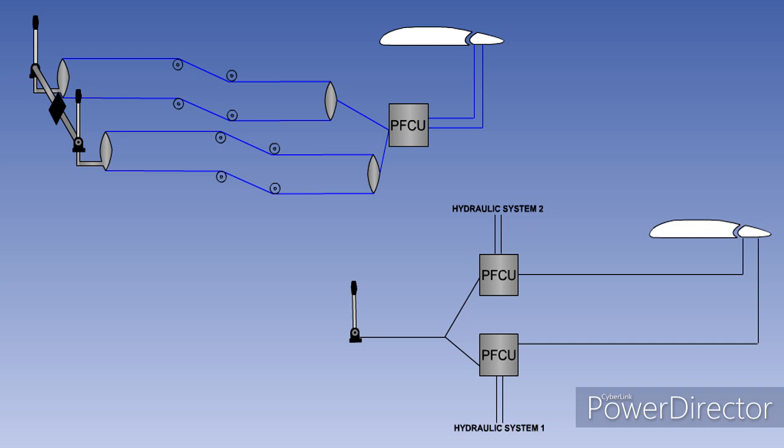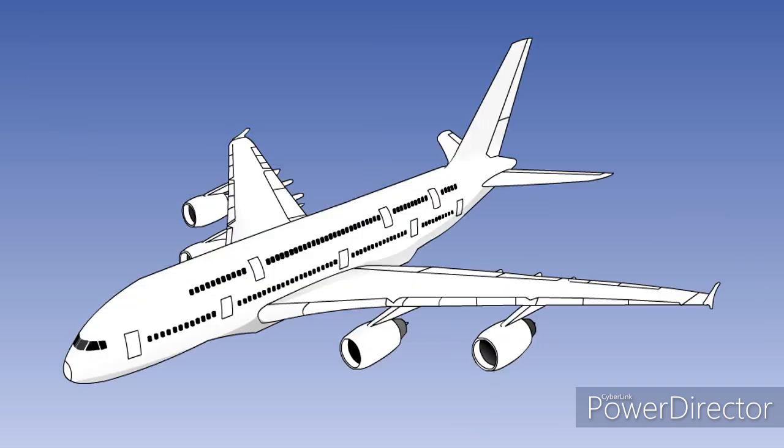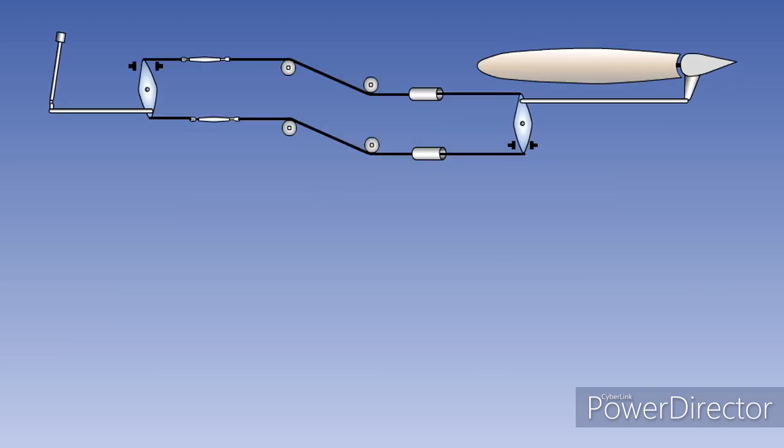In this lesson, we will examine the fly-by-wire flight control systems, in use on many of the most modern large aircraft. Mechanical and hydromechanical flight control systems are heavy and require careful routing of flight control cables through the aircraft, using a system of pulleys and cranks. They also require a lot of maintenance, in the form of lubrication, tension adjustments, and so forth. These systems have a very limited ability to prevent dangerous characteristics, such as stalling or spinning.